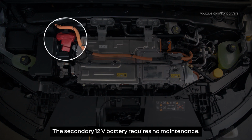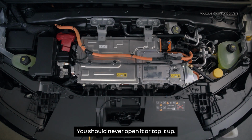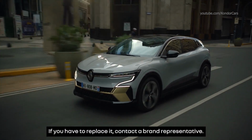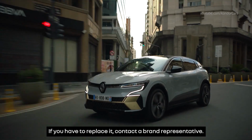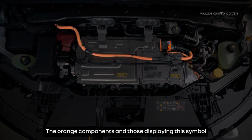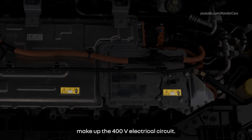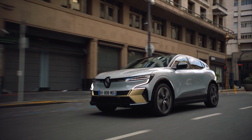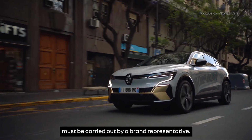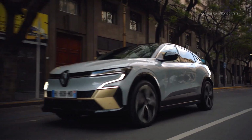The secondary 12-volt battery requires no maintenance. You should never open it or top it up. If you have to replace it, contact a brand representative. The orange components and those displaying this symbol make up the 400-volt electrical circuit. Any work on this high-voltage electrical system must be carried out by a brand representative.